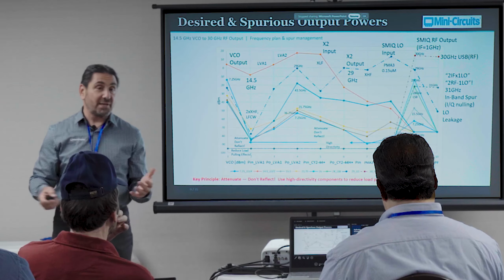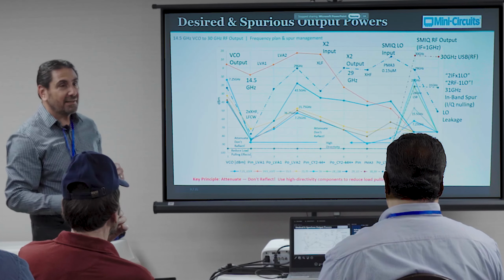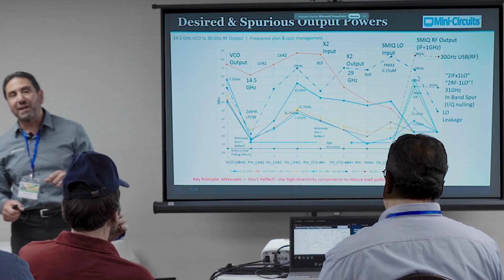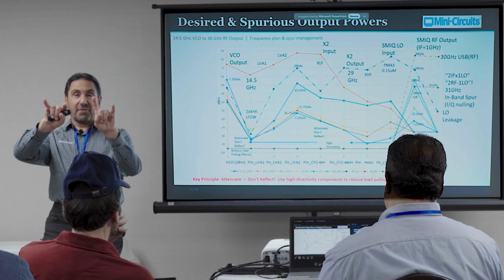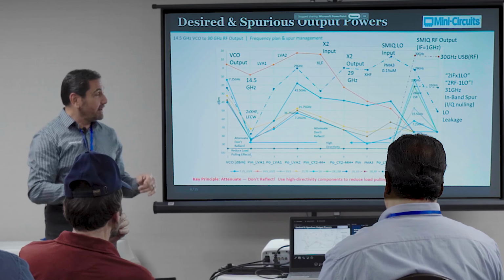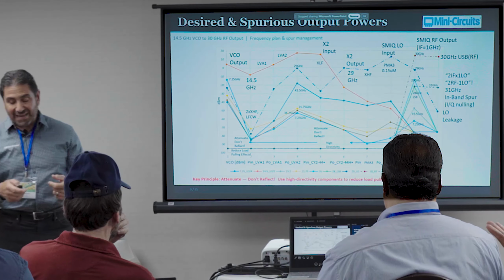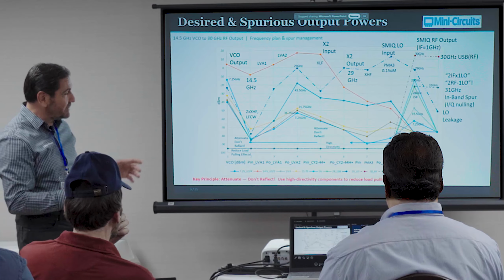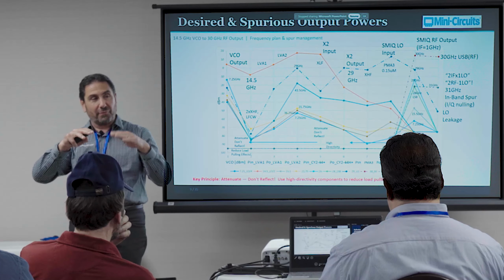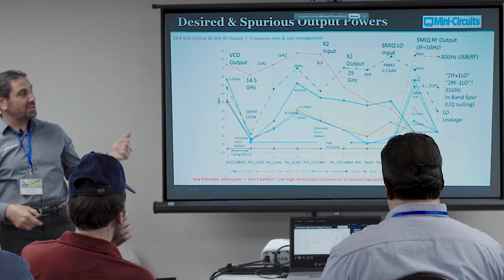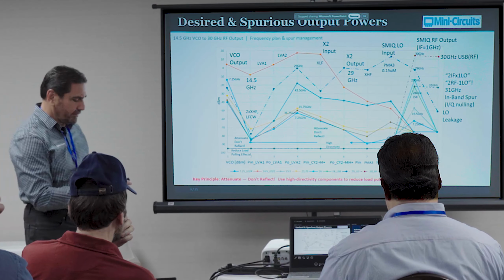So we know it's not coming from there. It could be a 2x1 in the mixer, right? We know it's not that. But it could also be a third-order product, and this is what gets some people. It could be a third-order product between the LO leakage and the upper sideband, causing a 31 and a 28 gig tone. And what you're seeing here is actually the result of third-order distortion, either in the mixer or in the amplifiers that follow. So you've got to be careful about that LO leakage. We have nulling pins on the IQ inputs that we can use to balance each mixer, and that'll attenuate the LO or reduce the LO leakage, and that tends to reduce the spurious also. So I didn't put data in, but we can get this down to minus 60 dBc.